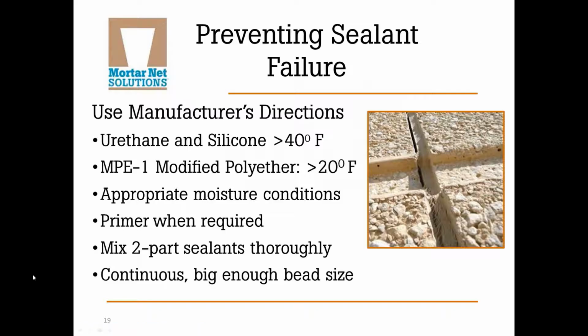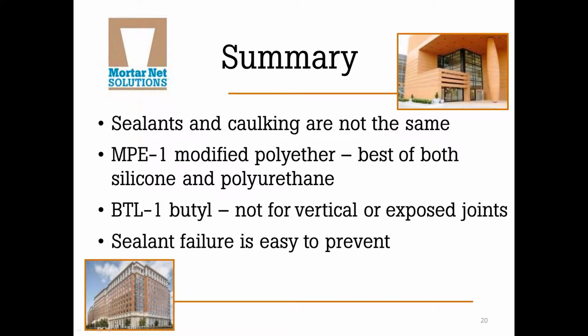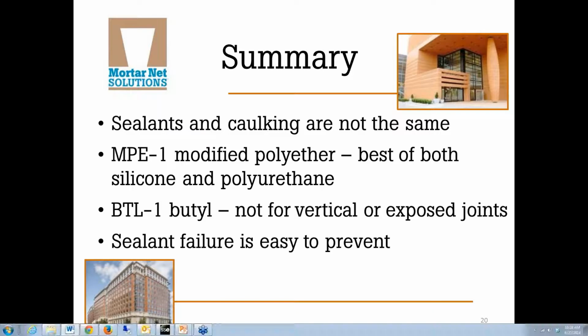So let's go ahead and summarize what we've been talking about. Sealants and caulking are not the same. Caulking is fine for indoor use, but commercial grade sealants are the only way to go for exterior applications in commercial masonry projects. Make sure the sealants you choose are compatible with your project's material. Silicones and polyurethane sealants have been the go-to sealants for a long time, but a newer type of sealant,